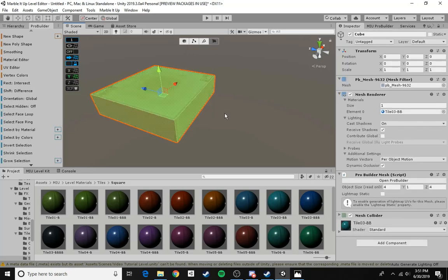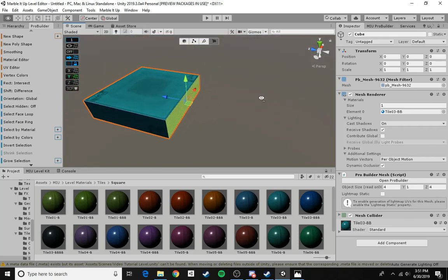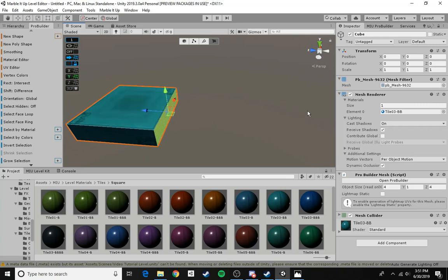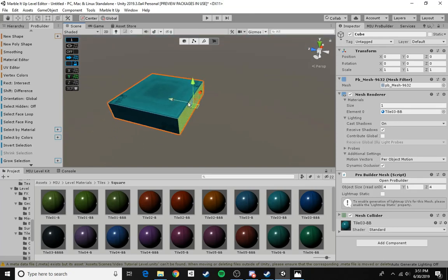So let's make a basic start area. Since this is centered, we'll use this as the start area for the level. I'm using face selection, and I'm gonna expand the face out. I'm basically gonna extrude it. Extruding is something you can separately do in this. If extrusion is more your build style, then you can use Control E and it'll extrude.